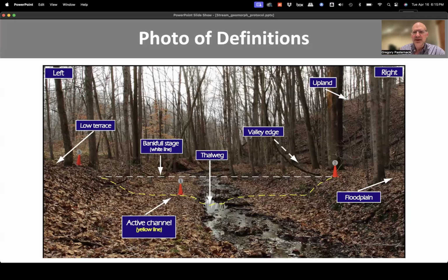Did I say riverbed before? I meant the base flow channel here. The base flow channel left and right toe, the left and right base flow channel top. Then you have the actual riverbed. So the active channel is this whole line, and presumably they've pushed the leaves out of the way and confirmed that there is active sediment transporting along these banks. But I would differentiate the riverbed toe at the slope break over here and over here, and then the active channel top, which in this case is being interpreted as a bankful stage. So you could call this the left and right bankful top.